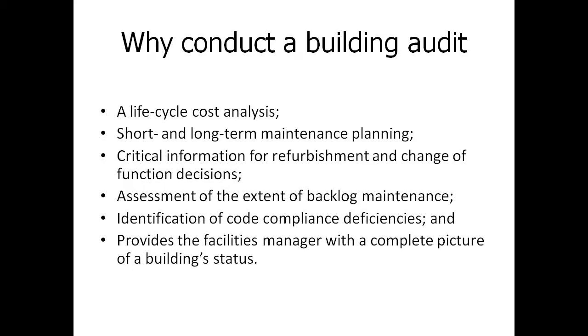The information gathered during a building audit is extremely useful to feed into the life cycle process, to actually work out where you are, drawing a line in the sand, what type of condition, what type of risk the building is at now. And from that, then we can start planning short and long-term maintenance. So it's also critical information to start scoping refurbishment and major rehabilitation of the building.